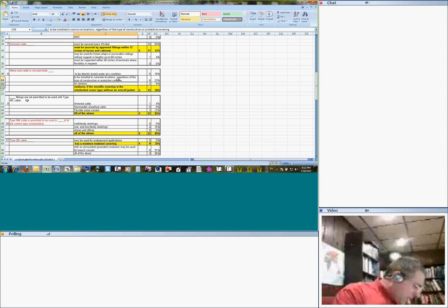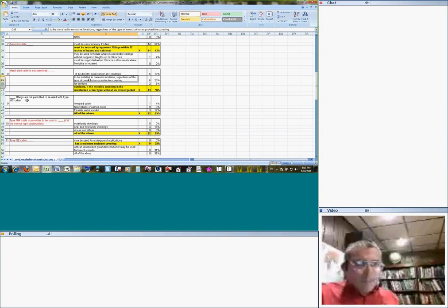Let me see. I'm looking at MC cable here. Use is not permitted where subject to physical damage or destructive corrosive conditions in A or B unless the metallic sheath or armor is resistant to the conditions. So I can see buried, direct buried, or exposed to cinder fills and so forth. I guess the confusing part is that it says not permitted. So yeah, it could be permitted if it's rated for it. But it says regardless of the type of construction.